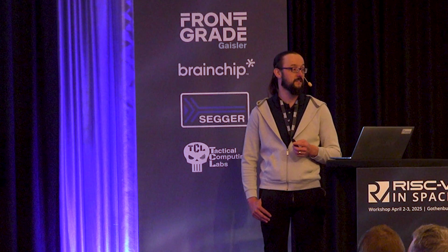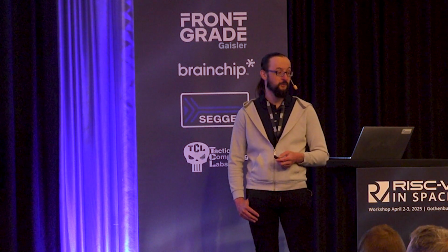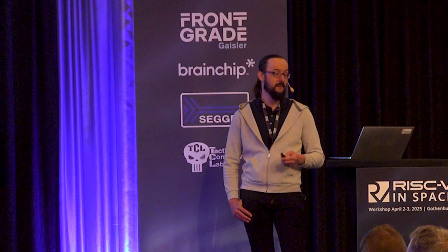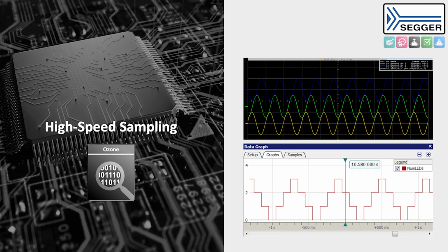This is usually done using system bus access, because the other options need to temporarily halt the system, which impacts real-time behavior and execution. And since system bus access is almost non-intrusive, memory can be read at higher frequencies without interfering with the core. Now, our J-Link debug probes feature high-speed sampling, so symbols can automatically be read at frequencies up to around 100 kilohertz. And this provides runtime system insight to variables and states by tracking values over time.